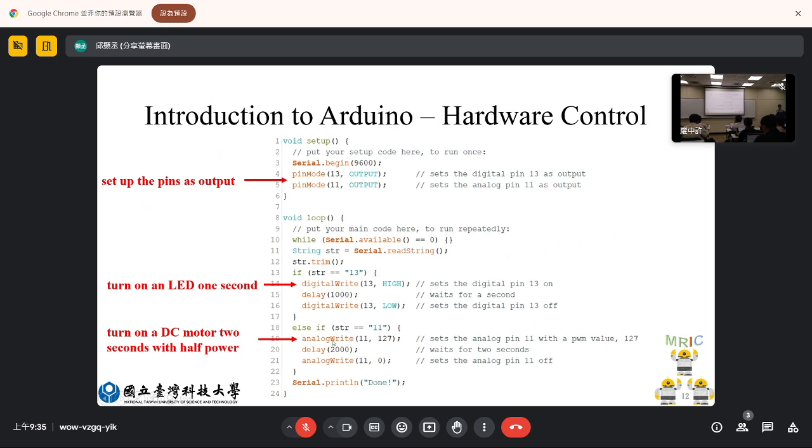Here, I would like to use an analog signal because we want to control a DC motor. For a DC motor, when we apply 3 volt, it can rotate, right? If we provide 6 volt, it can also rotate, right? They still have a range, probably from 1 volt to 13 volts, but in between, it can rotate no matter what the value is.